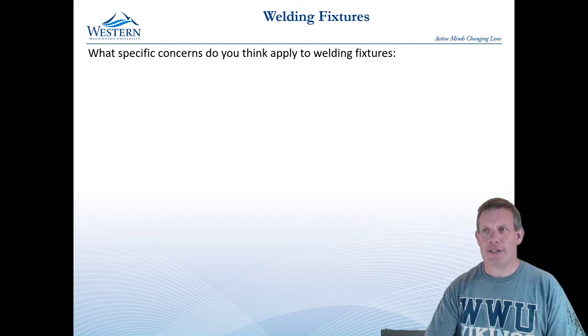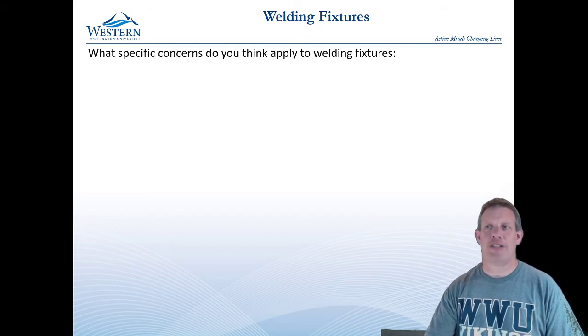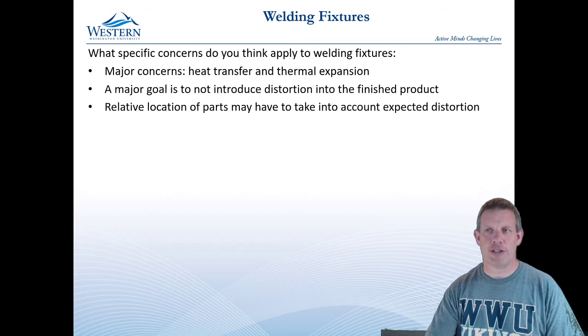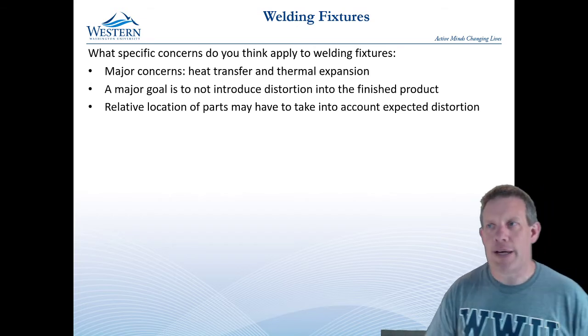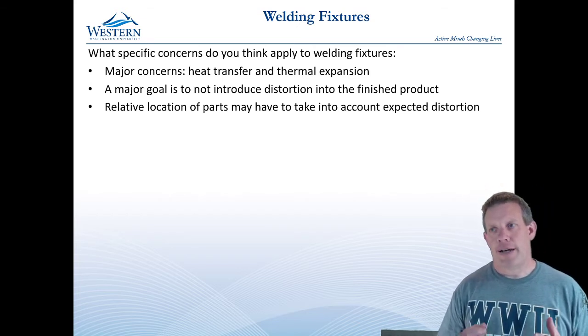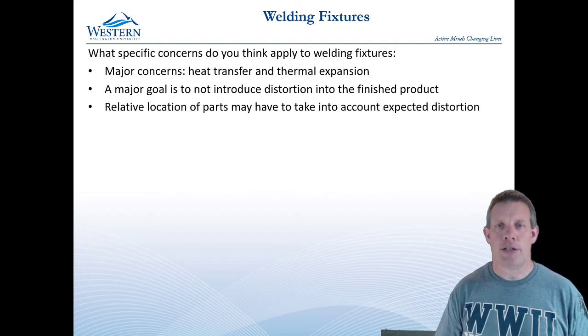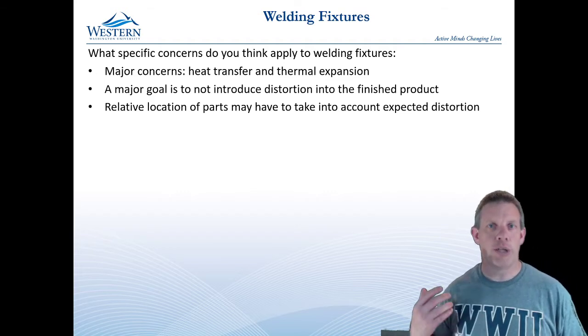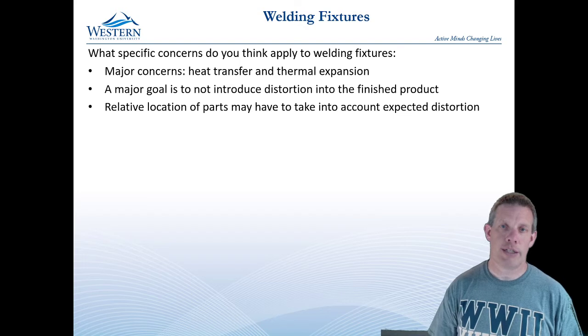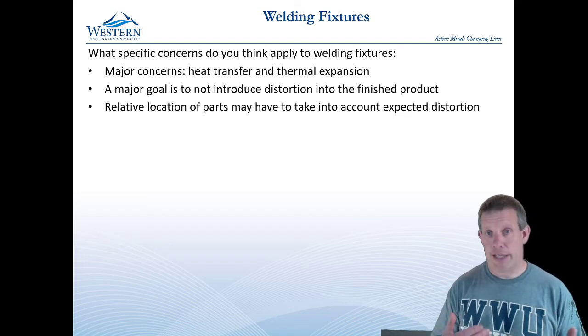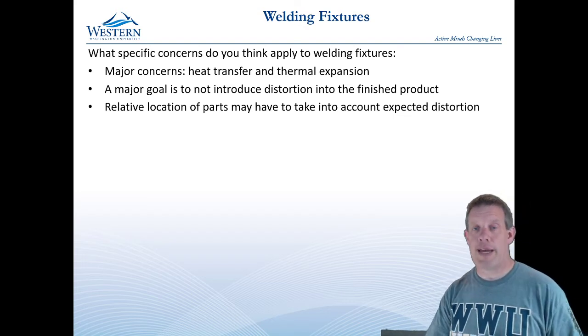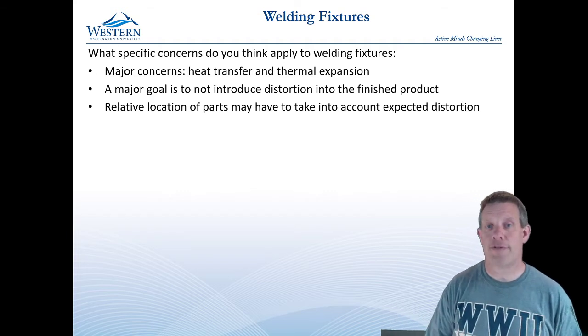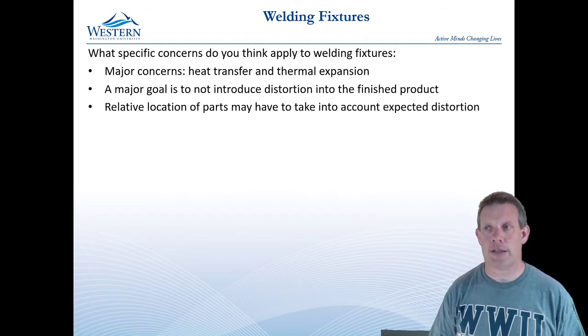So what specific concerns do you think would apply to a welding fixture? If you start thinking about them, the heat transfer and thermal expansion is one of the biggest. We're dealing with a ton of heat when we're doing welding, and so we may have to keep that heat in the weld, or we may have to get it out of the weld, but we're going to have to deal with it, and we'll look at that a little bit.